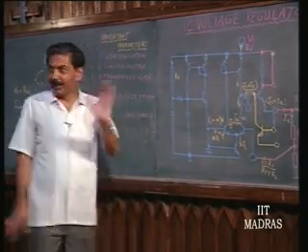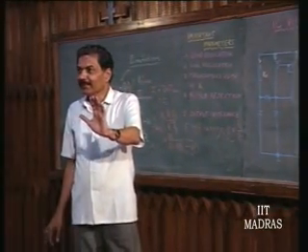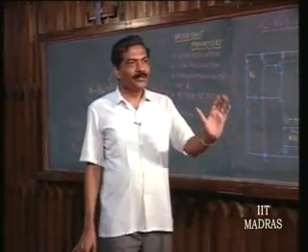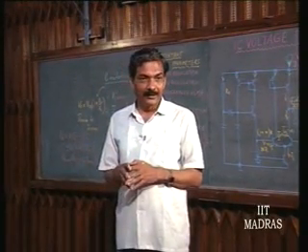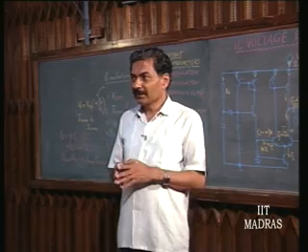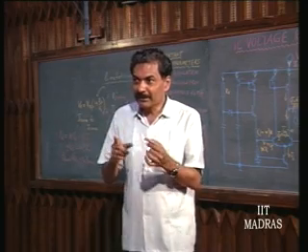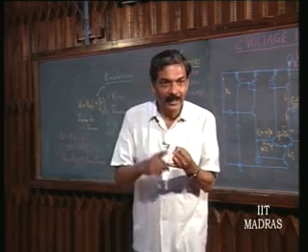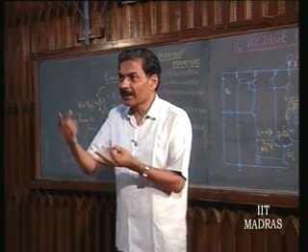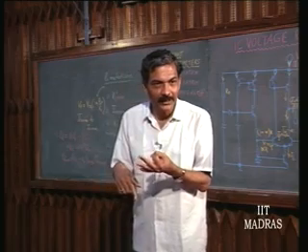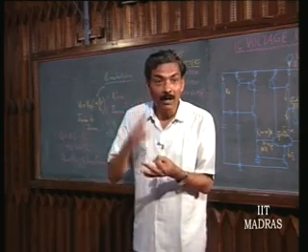So, the third limitation now, I naught max can occur simply because the transistor says that current cannot be passed through it. I naught max. Transistors themselves will have maximum current of operation, maximum voltage that can occur as reverse bias voltage between collector and base, and maximum power dissipation.